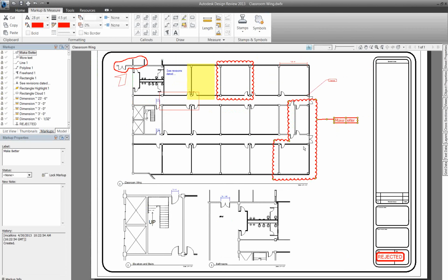You can share those catalogs also, so other people can get a catalog of blocks, essentially, that instead of being put directly into AutoCAD, get placed into the DWF as a symbol. Later on we'll see that we could then view those in AutoCAD, if somebody else is then intended to actually place the working live block into the CAD file, or Revit for that matter.